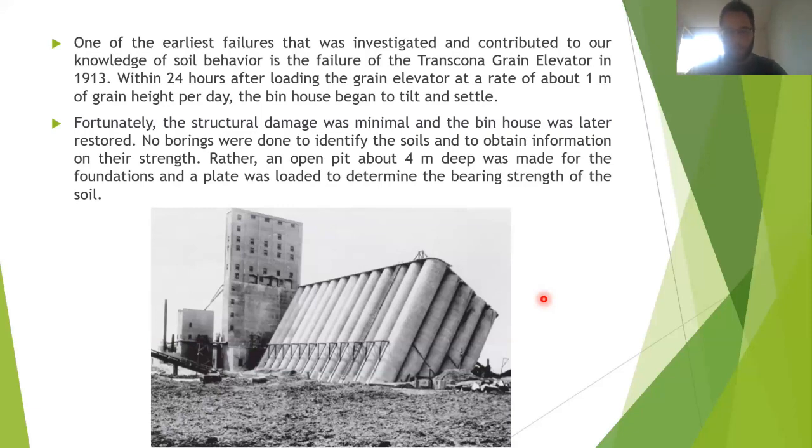But for chemical properties, it's easier. For example, in Eurocode, there's one norm, 206, related to concrete in general. There's one thing called classification of aggressivity on concrete. One parameter is the water that is interacting with concrete, and another one is the soil interacting with concrete.